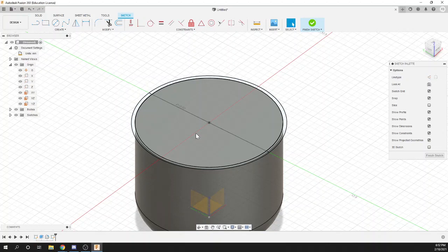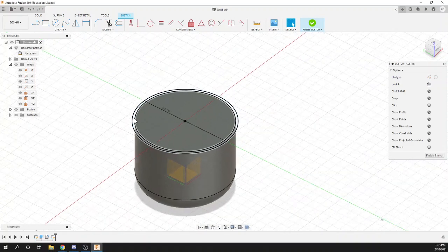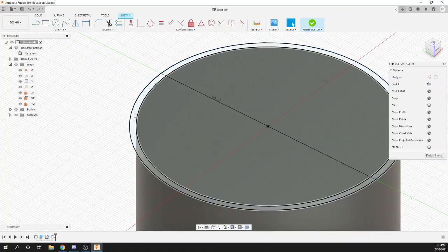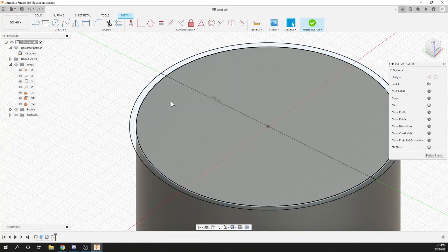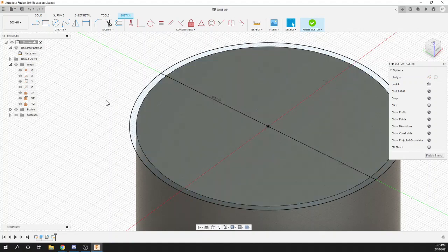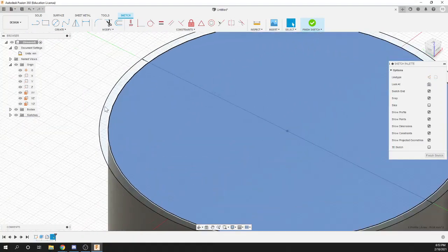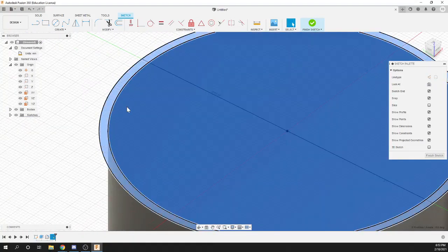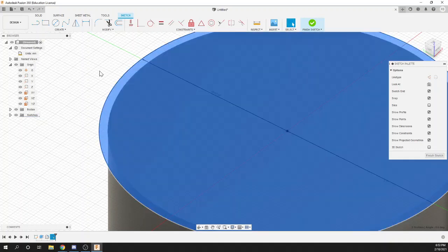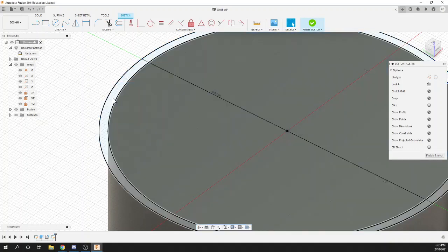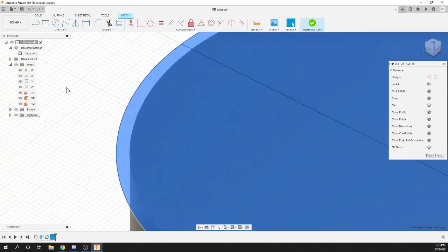If you mouse over here, you can see we have our outer boundary, which is infinite, so we can't select it. Then we have this inner portion formed by the two concentric circles, and then we have our innermost circle as well. To create this metallic part in our pencil, what we're going to do is select this inner one as well as this outer one. To do a multi-select, press down the Shift key and select both of them, and they should both be highlighted.